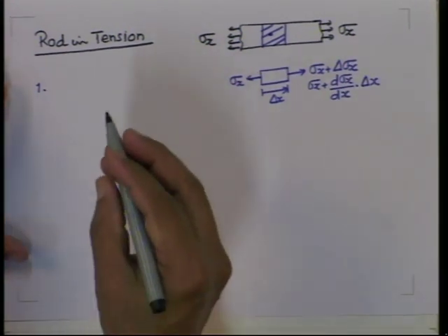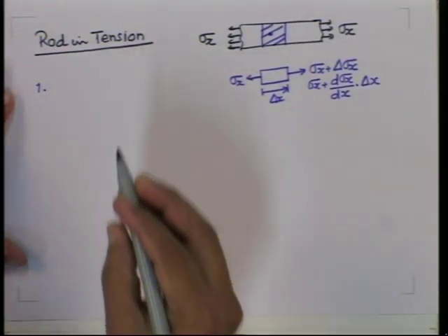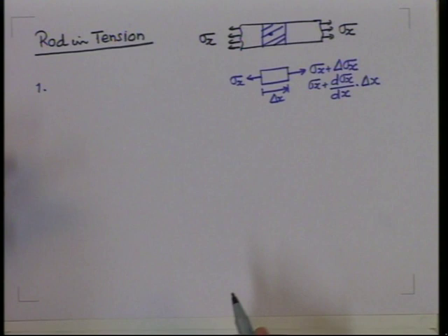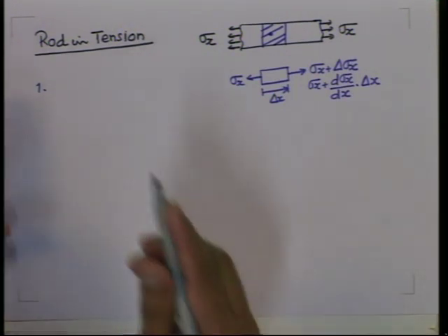If you recall your elasticity equations, there are three equations of equilibrium in 6 stress components, 3 normal and 3 shearing. Now, this axial rod in tension has only one non-zero stress component; sigma y, sigma z and all the tau ij are 0. So, the only equation left will be the first equation,